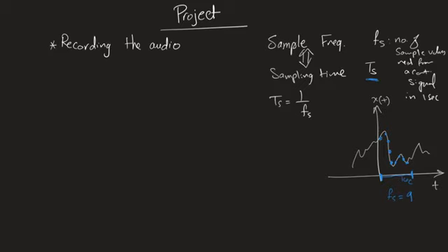So again, after you record your signal, the next step is you can plot the signal, and I will show you, by the way, example code that allows you to do this very simply, okay? So after recording your signal, you start by plotting the time domain. I warn you, when you plot the time domain, you will see a graph like this in MATLAB as a function of time. And this is your voice or x of t or whatever.